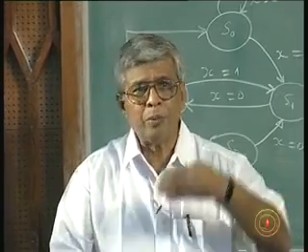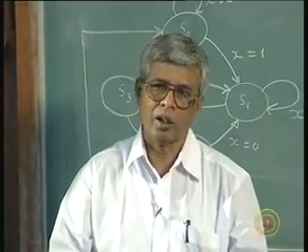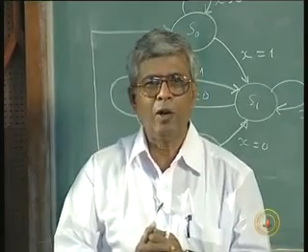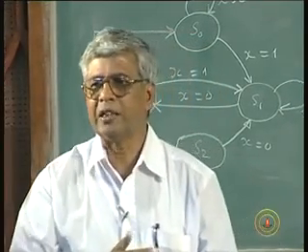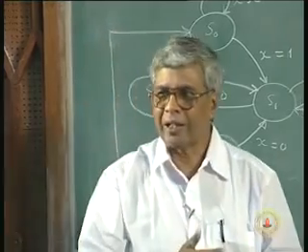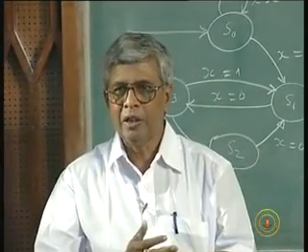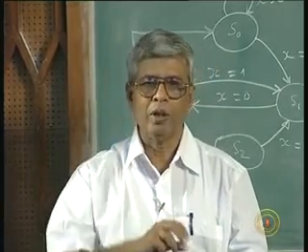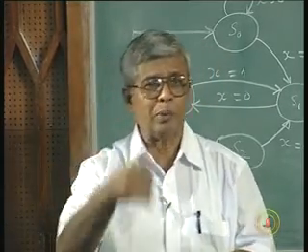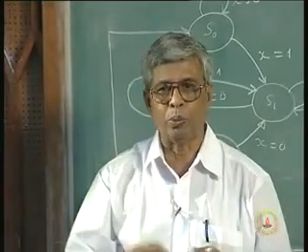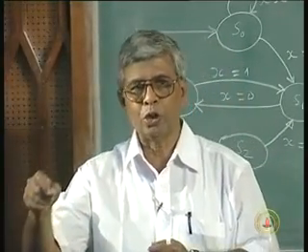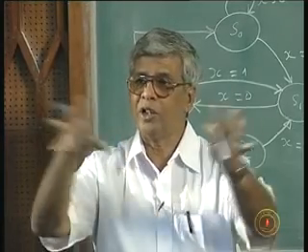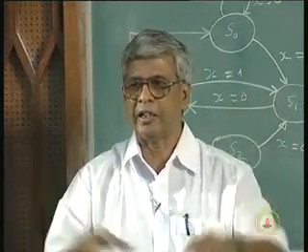So in order to determine the behavior of this machine, system, or circuit, I need to know what state the circuit is in now, and what input is likely to occur, and what the options of the input are. If the input is 1, what will happen? Or if the input is 0, what will happen? There may be more than one input: zero inputs, one input, or two inputs. Then X1, X2 can be two inputs: X1 X2 equal to 00, 01, 10, 11. There are four different conditions and four different states it can take as next value.